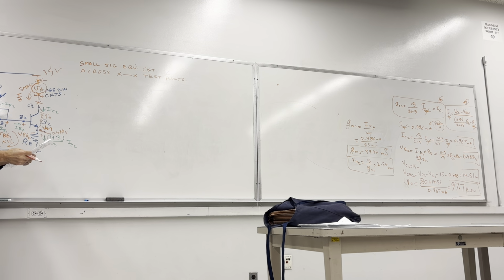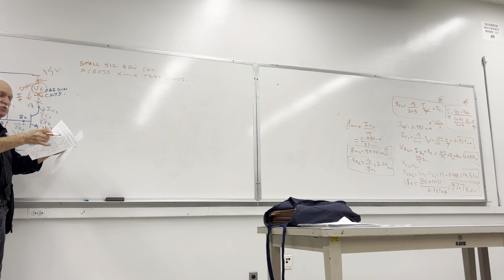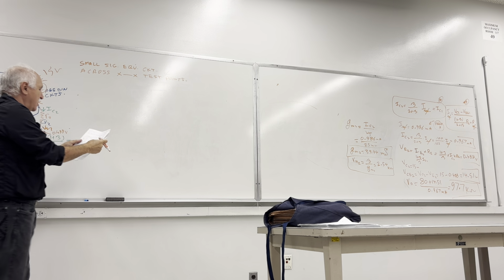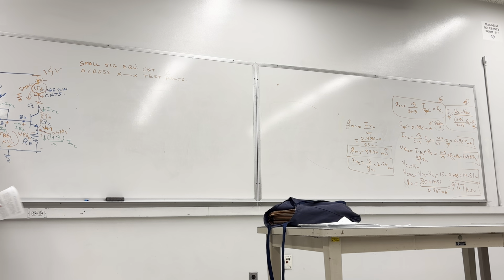Okay, so you've got to go to the previous problem and start drawing the model. So this will be the model. Transistor on the left, this guy. We've got an RO for that transistor, collector to emitter resistance, which is almost the same as the RO for this side. Although you can argue, well, here, VCE is only 0.7 volt, but VCE is much larger.